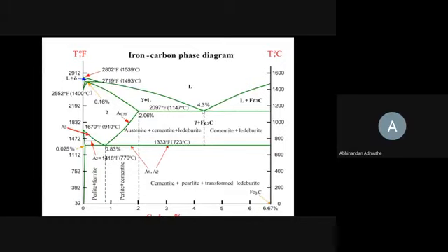So eutectic point means above which we have liquid and below which we have solid mixture. There is no liquid plus solid region present at the eutectic point. Off eutectic, somewhere here, you can see a liquid plus solid region exists. Similarly here, a liquid plus solid region exists, but exactly at the eutectic point, liquid transforms directly into solid. There is no liquid plus solid region.